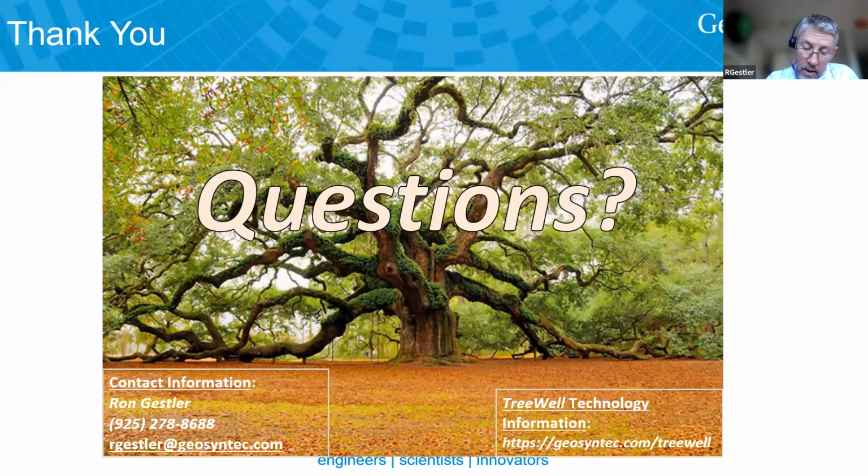Sorry. We've dug hard into this. We're specifically looking for funding to do some pilot studies where we would combine some number of these engineered phytoremediation units with an absorbent technology, probably GAC, granular activated carbon, where we would simply use the tree as a pump, and use that pump to pull PFAS-laden groundwater or a PFAS plume through a GAC zone that would be installed within that engineered phyto unit.